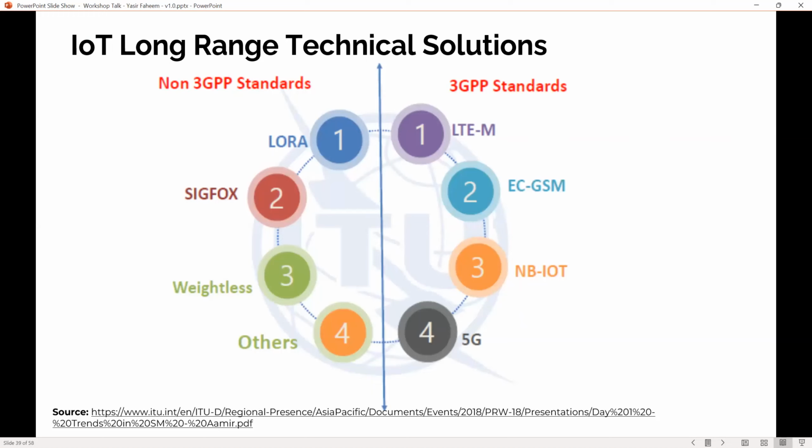These, especially LoRa and SIGFOX, operate in unlicensed spectrum, so you don't have to pay anything for the services. You have to pay only for the hardware. LoRaWAN offers a transmission range of 5 to 15 kilometers. In open spaces, it can easily reach 15 kilometers. SIGFOX is a similar competitor that offers longer transmission ranges compared to LoRaWAN. So personally, in regions like Islamabad, if we are deploying multiple IoT devices on a lake site, I prefer to use something like LoRaWAN. Okay, so data can be collected.